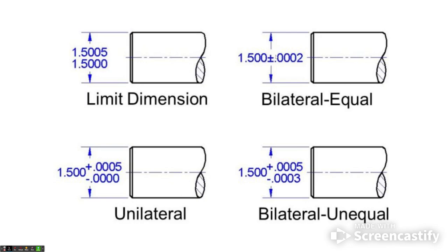Basically, the tolerance goes the same direction, so plus or minus in the same. We also have what's referred to as a unilateral dimension here. So where it's given to you as a plus 5/10 minus 0. Of course, that could also be the other way where it would be plus 0 minus 5/10, depending on what the design intent was with that as well.